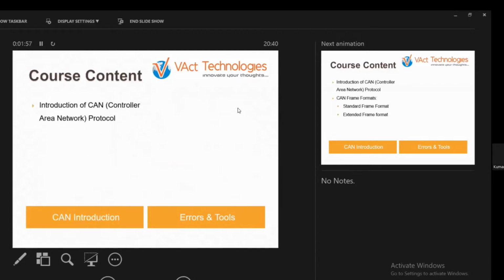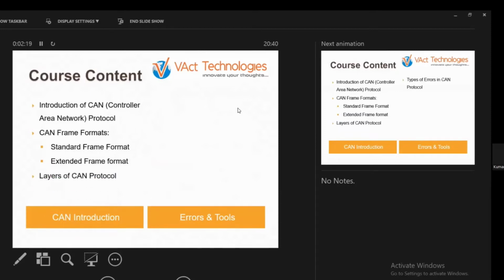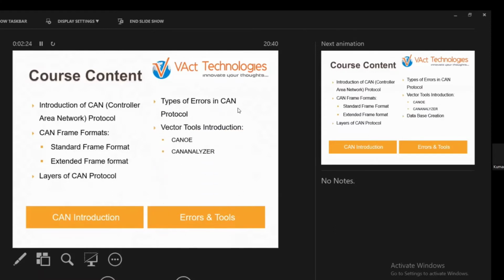What is the course content? This is about CAN, Controller Area Network. It's a protocol. We will be dealing with an introduction to CAN and the CAN formats you have. You have two formats: one is the standard frame format, another is the extended frame format. Then the layers of the CAN protocol, and the types of errors in a CAN protocol. We will also touch base on a CANoe introduction, how the tool looks, and how we will be writing CAPL scripting and things like that.